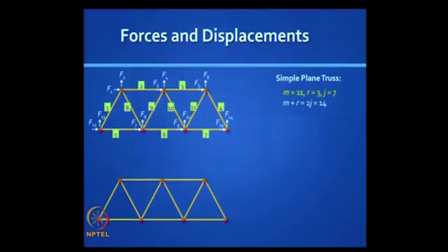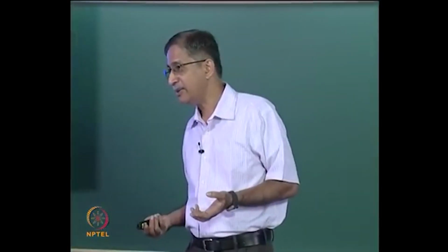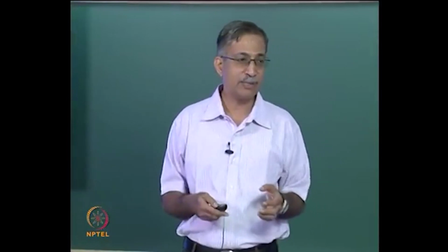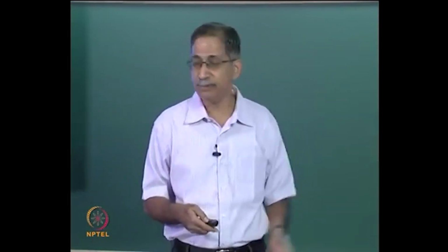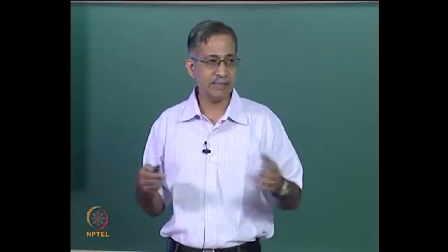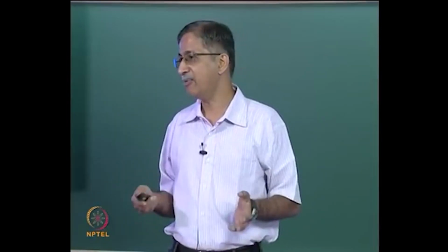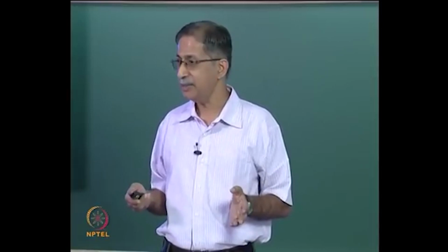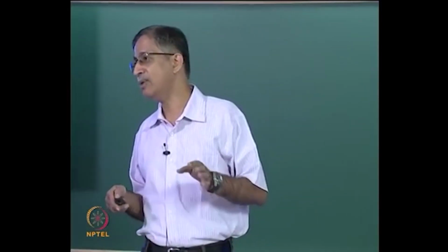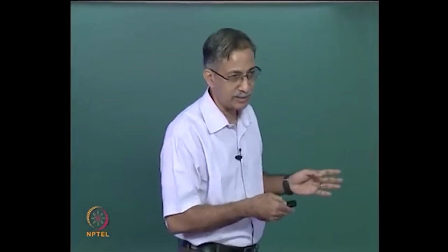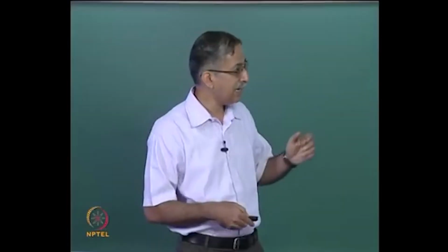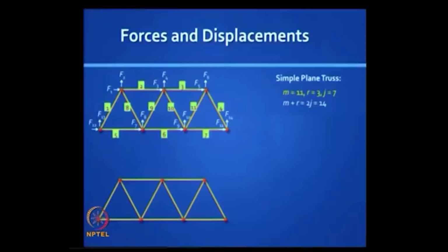Some of those joint forces are support reactions and some of those joint forces are potential loads, and with this kind of description you have a complete description of the external forces on a structure, some of which could be unknown reactions. Is it clear? So here I have shown a free body of that structure, but the force field in a structure also includes internal forces, and there are 11 bars in that structure.